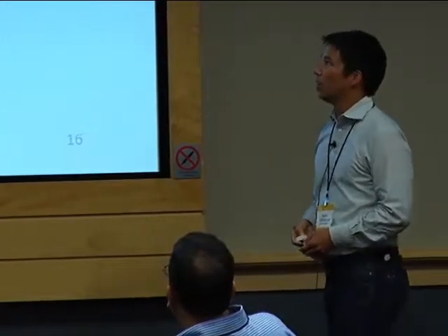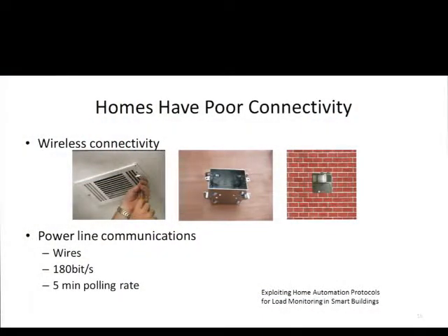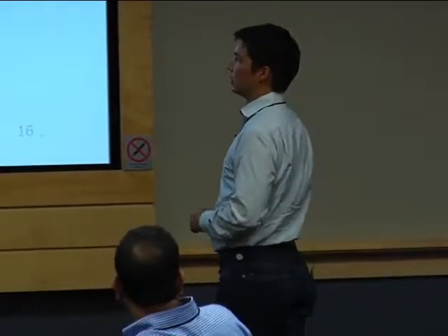We also found that they are not the connectivity panacea that we thought they'd be. Of course, getting connectivity across mountains or across fields is very difficult. We thought, a small house: Wi-Fi works in houses, laptops work in houses, so connectivity would be pretty easy. It turns out that it is for laptops on your couch, but it's not so easy when you start deploying sensors all over the house, for example in metal air ducts, or in metal junction boxes, or on masonry walls.